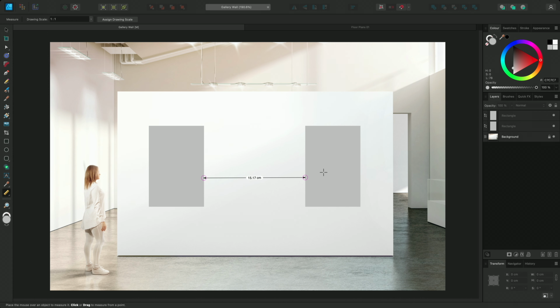If you need to adjust the start or the end of the measurement, you can hover over the end that you'd like to move, and the cursor will change. Then you can either click-drag the point to a new location, or click once to lift the end, and click again to release it. These measurements are not permanently displayed, and they do not appear on prints. They will disappear when a new measurement is made or a different tool is selected.